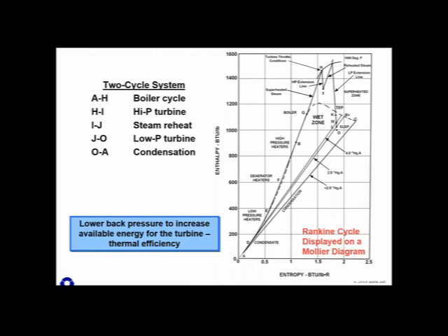So let's take a look at how the condenser affects efficiency of the Rankine steam cycle. This chart is a Mollier diagram that shows the enthalpy, or energy per pound in the water throughout the steam cycle, versus the entropy, or the energy that does not contribute to work. It's really essential to understand this chart because it's the basis for developing algorithms to determine efficiency of power generation and ultimately valuing your effort to improve condenser performance. It's a great tool to describe why we care about the condenser.